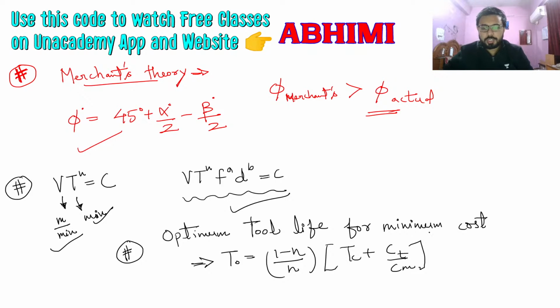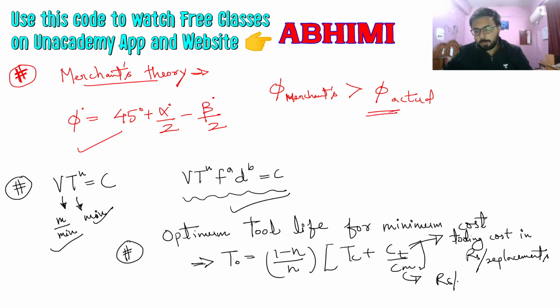This Tc is tool change time, this Ct is tooling cost, and this Cm is machining cost in rupees per minute. So again you have to remember this machining cost is rupees per minute, this Tc is tool change time, and this (1 minus n) by n is for optimum tool life for minimum cost.